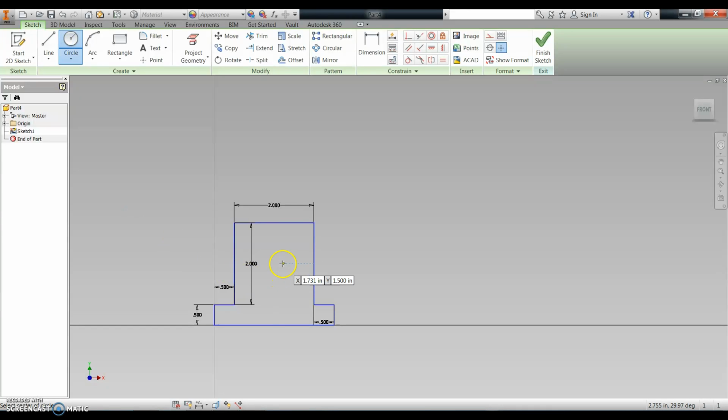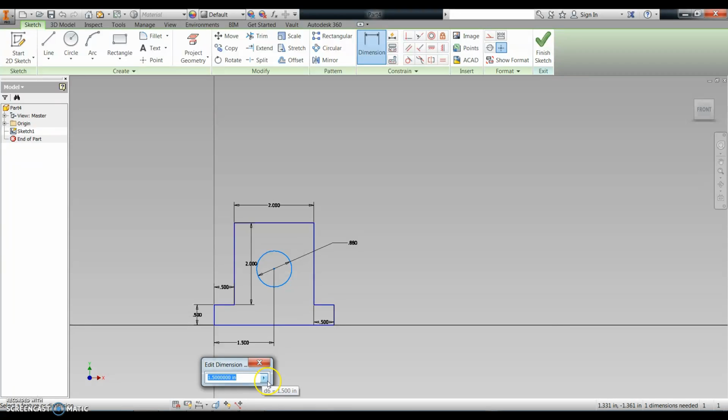I'm going to go ahead and locate the circle. So I'm going to put the circle on here. As you see when I'm projecting there, it's locating this part 1.5 inches. So if you can find that point, you might as well go ahead and put that in with the 0.5. I'm just going to sketch here and then apply the dimension. This is a 0.88 diameter. The center to this corner right here has already been specified as 1.5 inches. And then I'm going to locate the dimension from the bottom. So from the bottom edge, it's up 1.5 inches. And that's going to specify that.